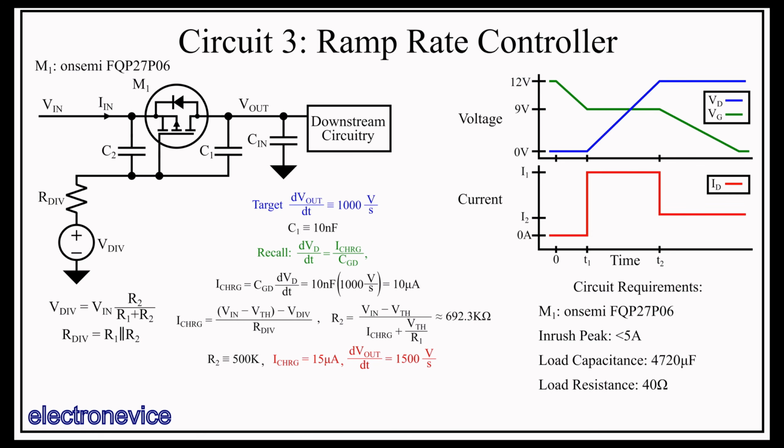In general, this method is likely to predict a higher peak current than reality, especially since the plateau voltage will be a bit lower than the threshold, as a significant amount of current will be flowing through the drain at plateau, and it takes a volt or so before the FET truly gets high transconductance. So let's move forward with the setup and we'll reevaluate if the lab results prove too high of a current. Finally, I set C2 to 100 nanofarads, which I'll explain later. Okay, now let's take a look at the completed circuit.